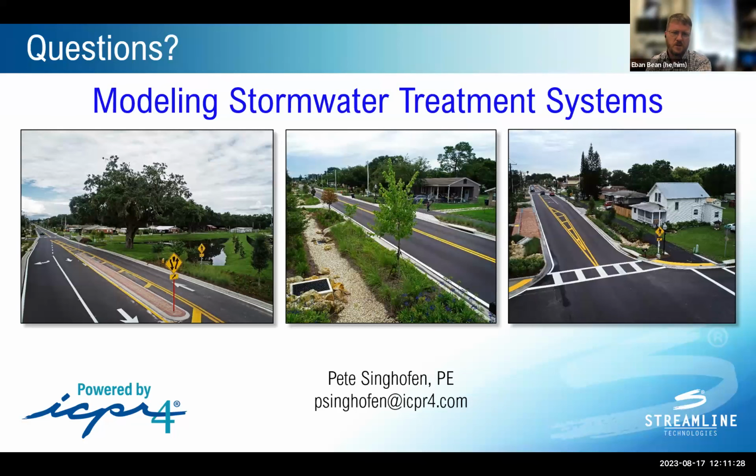The concern is when it accumulates too much sediment, it makes it even harder to remove whenever you do perform maintenance. So it's good to make sure that's done. Generally, without knowing specifics about different types of permeable pavement systems, we'll usually recommend at least trying to vacuum that out about once a year. That'll vary by application, setting, et cetera.